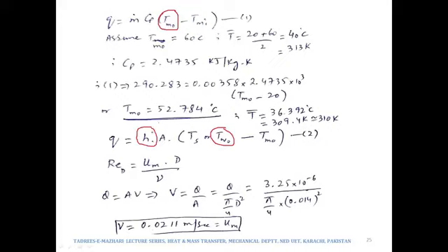So Reynolds number would now be written as Um and not U infinity times diameter over viscosity. We do not have the velocity, we have the diameter, and the viscosity can be found out from that table where we have found out the Cp from. If we use this simple expression of Q is equal to AV, we would be able to determine the velocity.